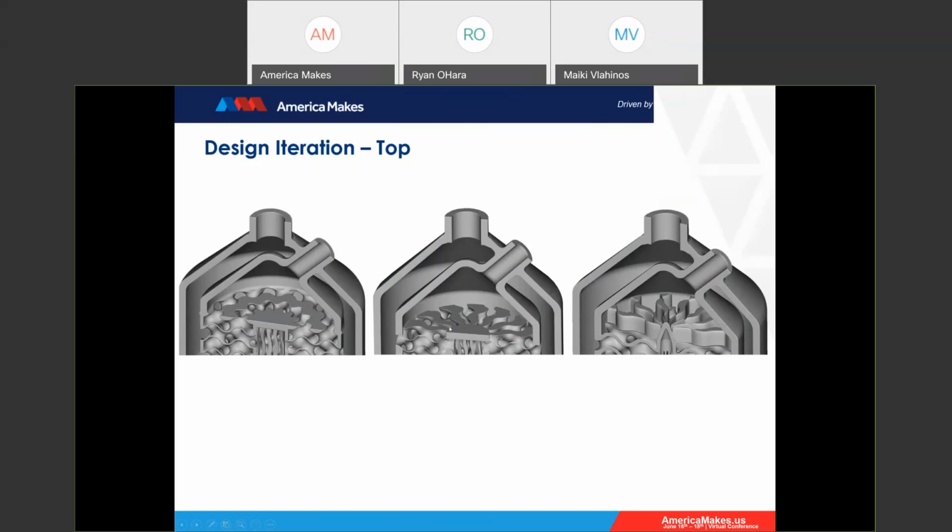And then we discovered, at least in this particular case, that if these vanes came out radially, we actually saw improved efficiency and flow overall. So just by adjusting a couple numbers, we're able to reshape this structure and simply improve the overall efficiency that way.